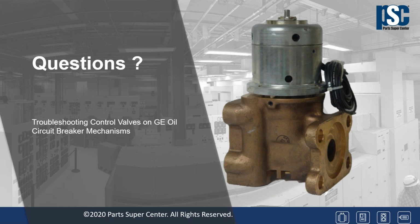So the tolerances on the fit between that piston and the valve body are plus or minus a half of a thousandth. So that's pretty precise considering these were designed and first built in the 1940s, late 1940s.